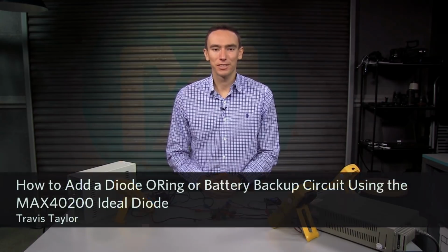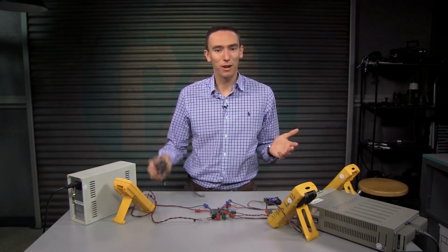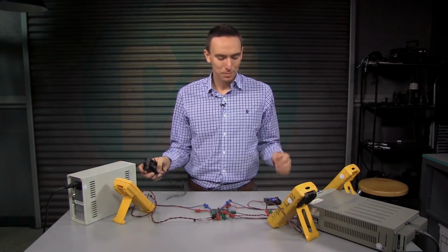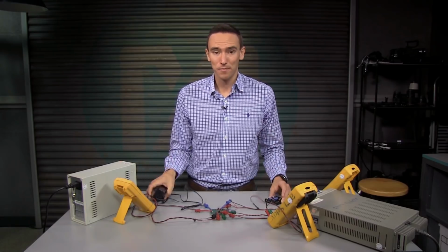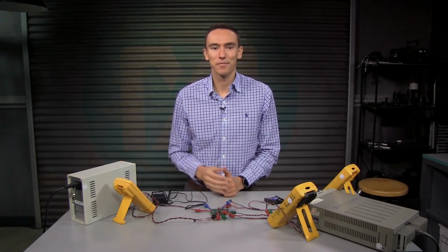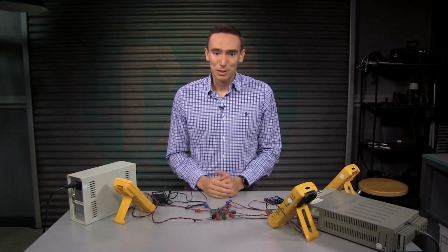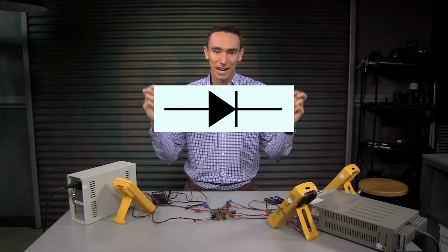When designing portable systems to have both an internal battery and a connector to apply power from a wall adapter or USB port, it's pretty common to use single-use, non-rechargeable batteries because they're cheap and widely available. However, there needs to be a way to switch between the two power sources that is efficient, safe, and seamless. Circuits that automatically switch between two power sources are called diode ORing circuits, even if they don't include any diodes, as they're named after the first component used to accomplish this function, diodes.